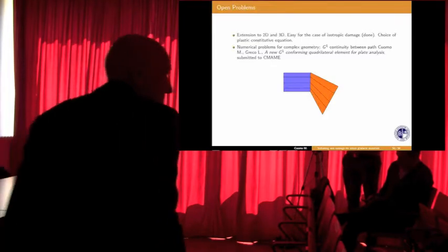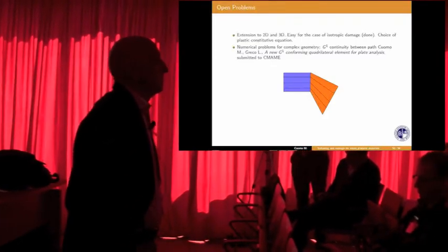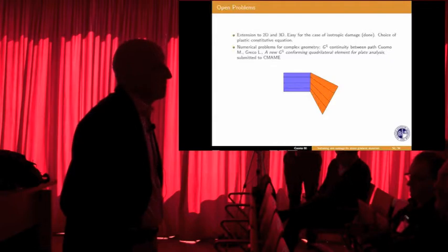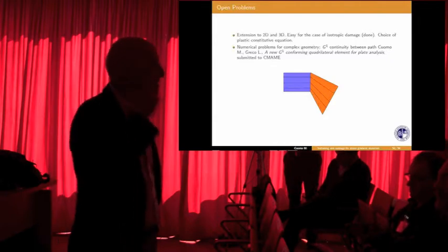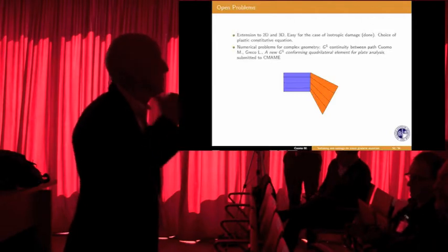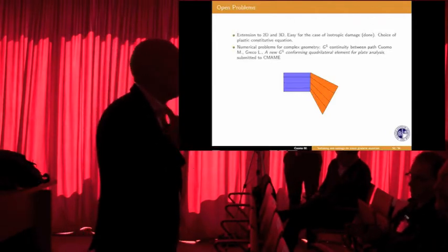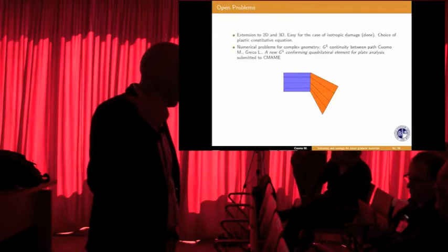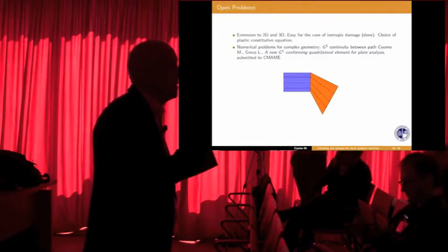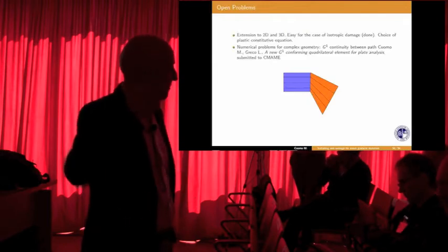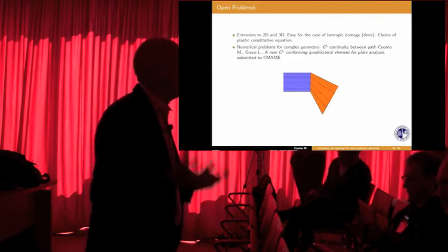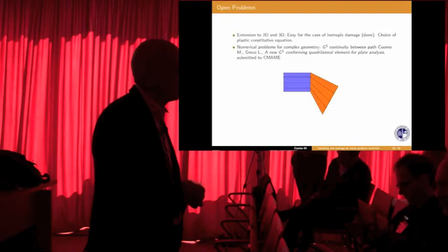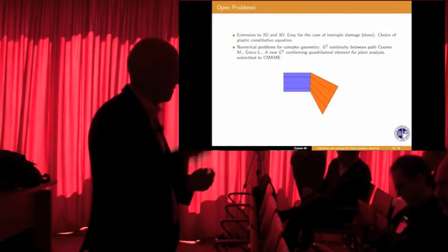What kind of arc length method have you applied to overcome these sharp corners? Well, actually, this is a trick. I did the simulation with the arc length, and I checked that I got almost the same results in many cases. Then I followed another way for these figures, because arc length is very tricky: in every case you have to adjust the parameters a little bit. So this is another way, like a shooting solution.